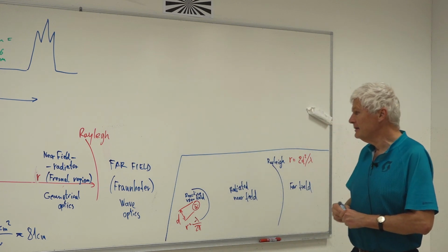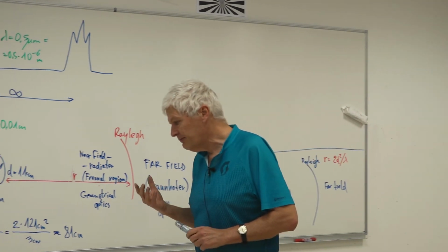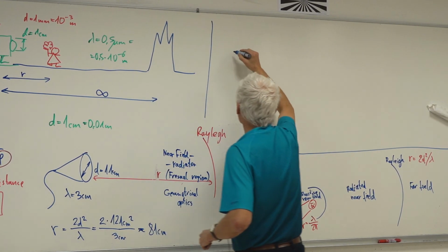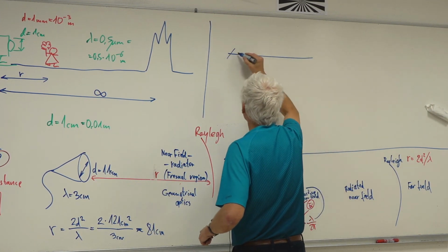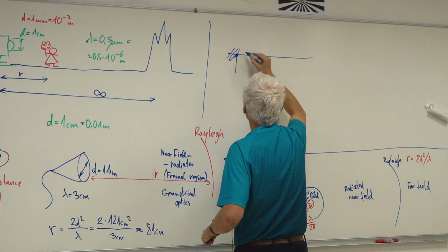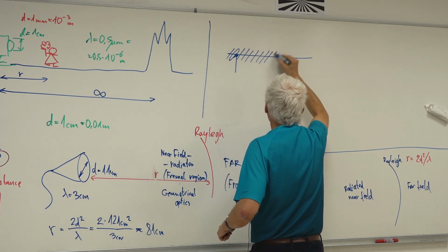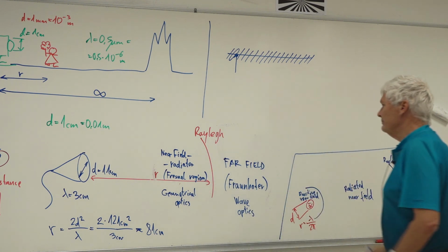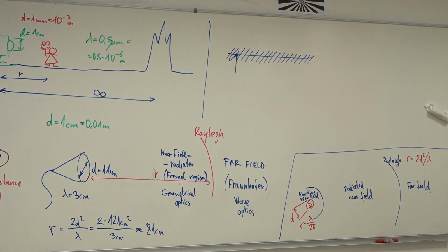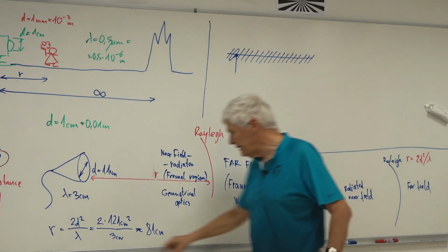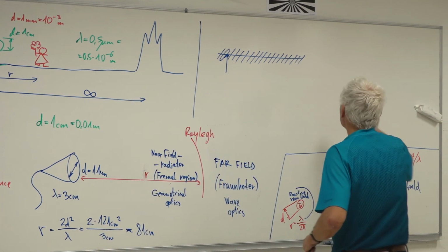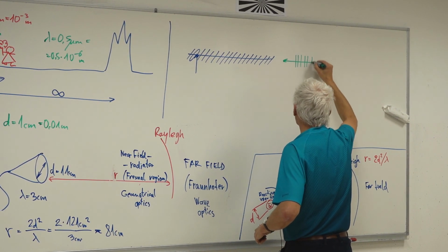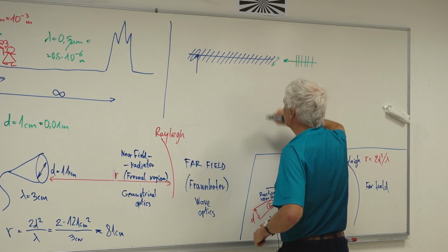There is yet another trick, understanding where the far field starts. The question is now what we do when we have a very long antenna. Where do we take D for such a very long antenna? If I am observing this antenna from the front, if my wave is coming from the front, then D is always the transversal distance.